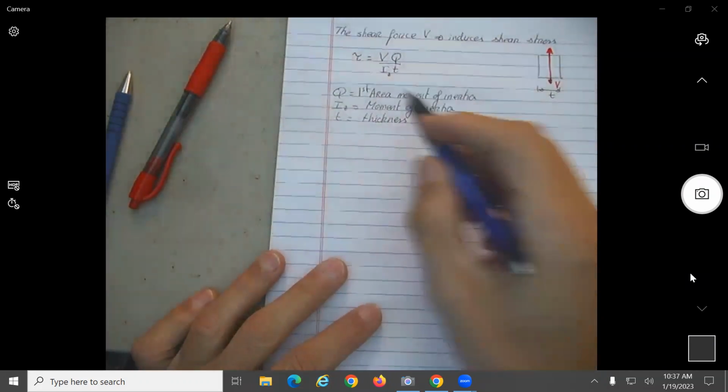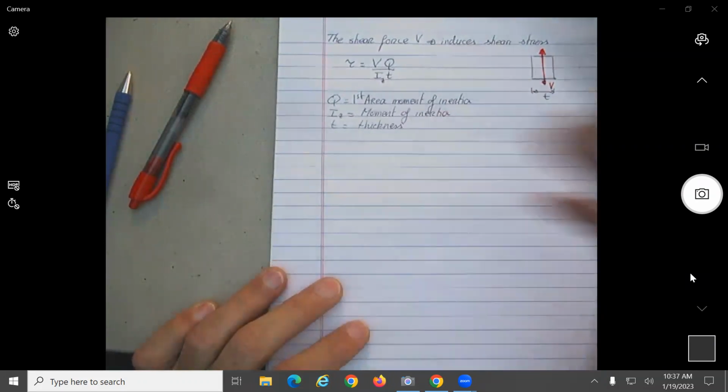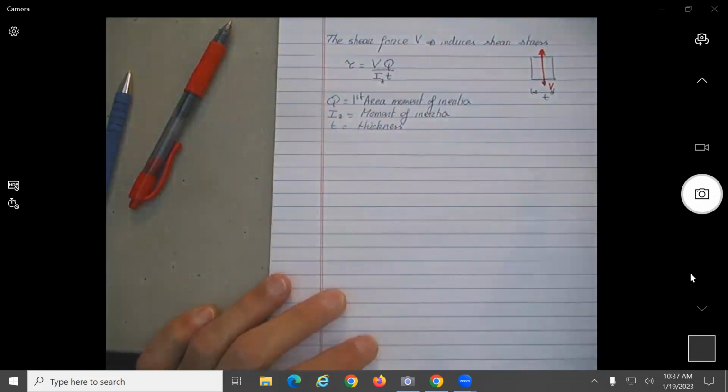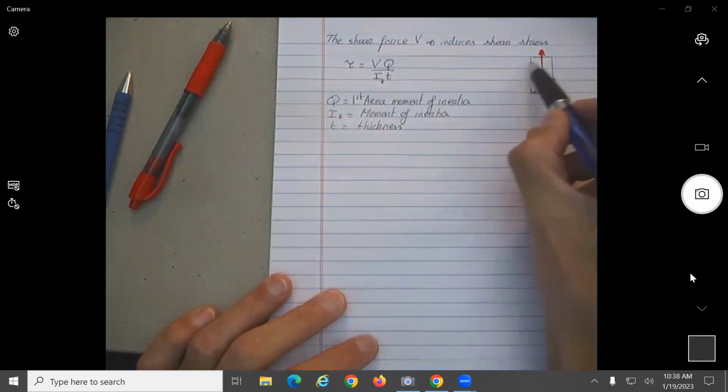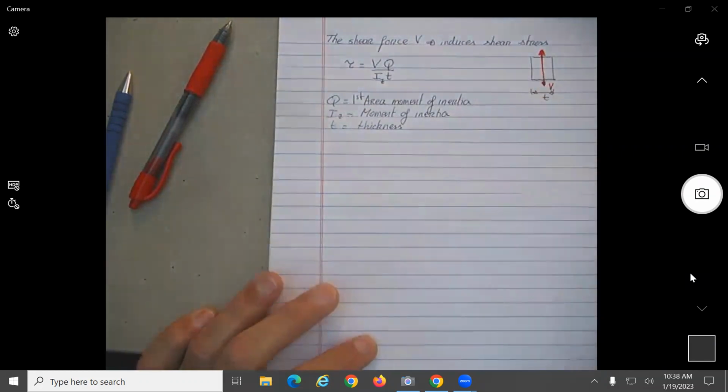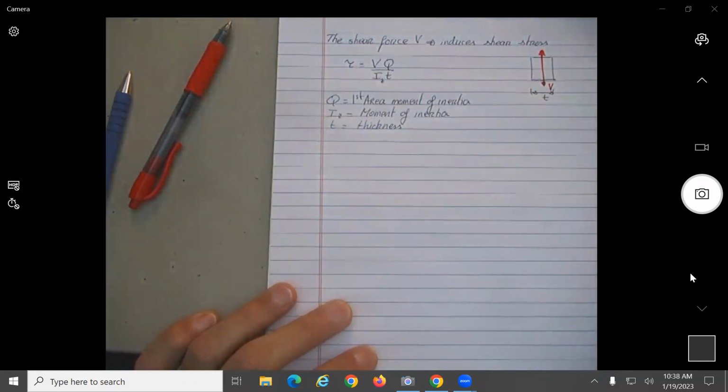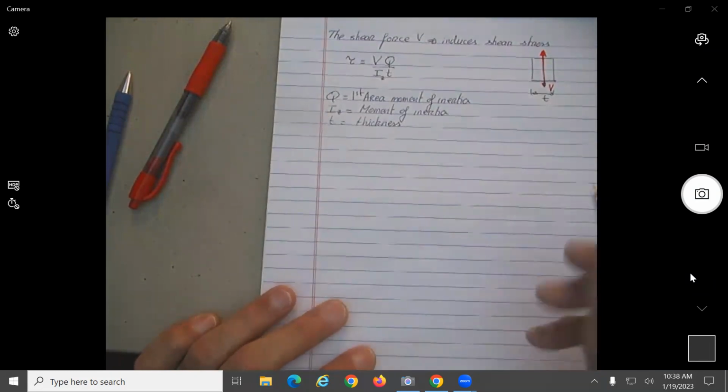So again, I will go back to this equation in a lot more detail, okay? Basically, when we need to, for example, design bolted connections, or if you put rivets or whatever, this becomes important, okay? But not for this, because the rivets or the bolts will break in what? In shear. So for these cases, this will be the important part, no? Okay? But for now, it's just beams, okay?